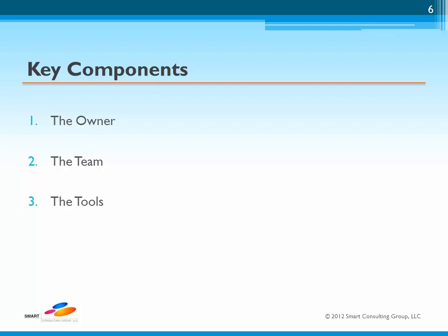The most effective way to learn value stream mapping is to perform the process using a wall chart and post-it notes to chart the various operations and data that are part of your process. This is so that one gets a complete understanding and appreciation of the mechanisms involved, and so that one does not overlook areas that may at first blush appear unimportant.